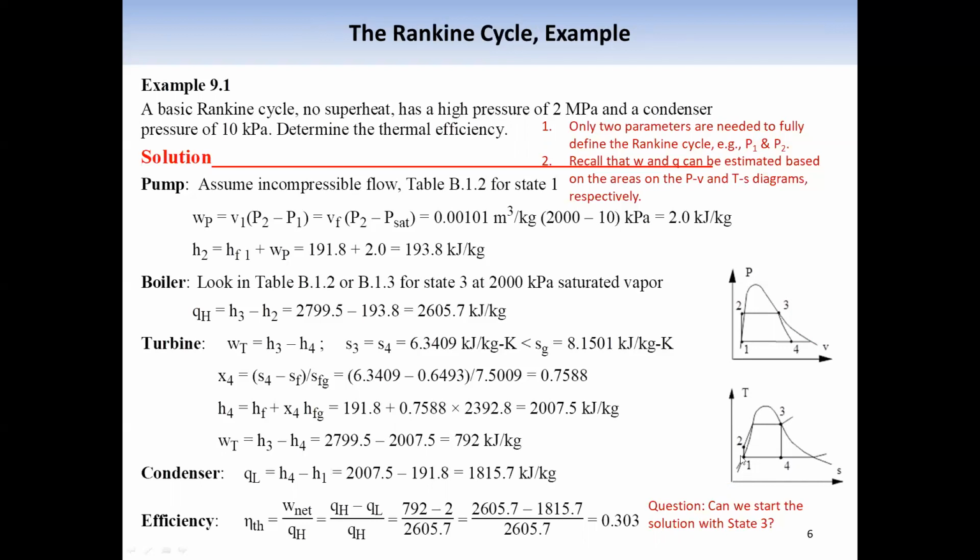State 3 and state 2 share the same high pressure, and state 1 has the same pressure as state 4. So we can start from the pump. For the fluid entering the pump, we are given the pressure. Because it's saturated water at that pressure, we know the temperature.